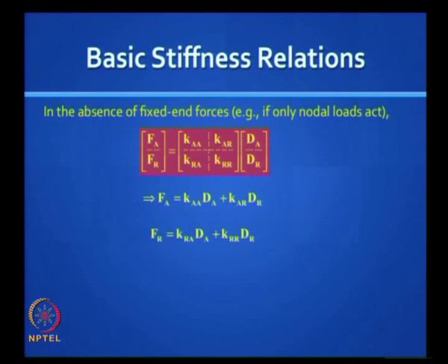But before that, let us say you have got the stiffness matrix, you can write relationships like this. Basically F is equal to KD at the structure level, but D itself is subdivided into active degrees of freedom, which you do not know, dA displacements, but you know dr displacement, right, they are usually 0. On the left hand side, the force vector FA is known to you, that is a load vector acting at the active coordinates. FR is the reactions you do not know, right.